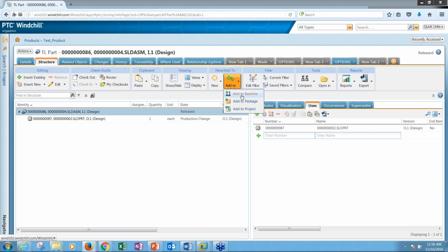If you're using the change process, the change notice doesn't automatically do the same thing. So a lot of times what we'll do is edit the change notice workflow, where once the change notice is approved and it releases all of those new objects or the new versions of the objects, it sends a task to one of the change administrators to go in and create that baseline. So they would go in and create that baseline. Now you know you're always going to have that there.